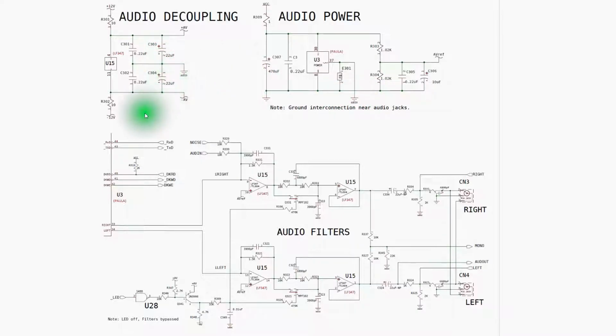You'll notice on the cap below that the negative 12 volt comes up to the negative lead, and the positive lead of the cap again goes to this audio ground reference, and that's because this voltage, this minus 12, is lower than the basically 0 volts we'll see here. And so because this lead is more positive in reference to this one, I have minus 12 and 0, the capacitor's in this orientation. So these are polarized capacitors.